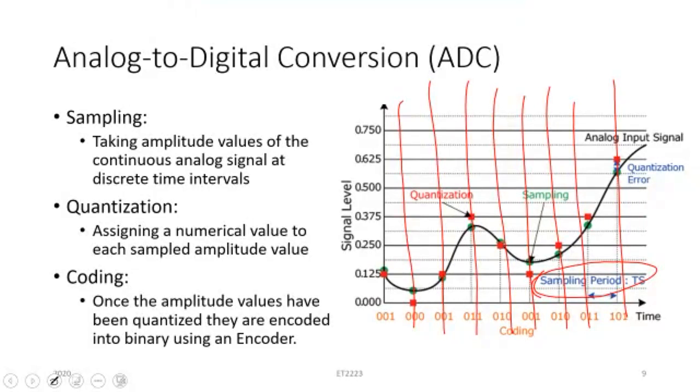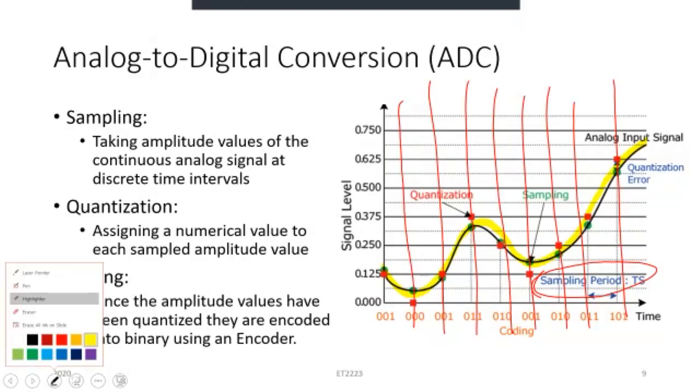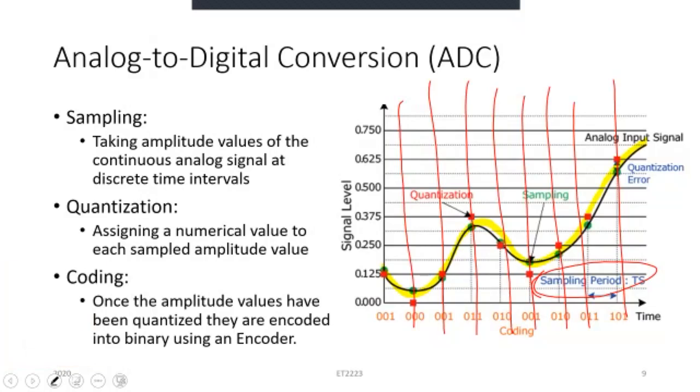So say this is the analog signal that we have. That analog signal will be there as it is. It is sound, for example. Then if you want to convert it into digital, we will observe at every suitable point in time, or every interval in time, and we will get a value for that. For each point, we will get a value. Whenever we are at that sampling point, we will read what the value is from that analog signal. So that is sampling.